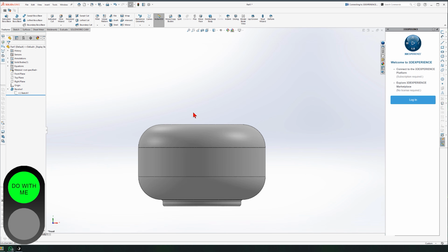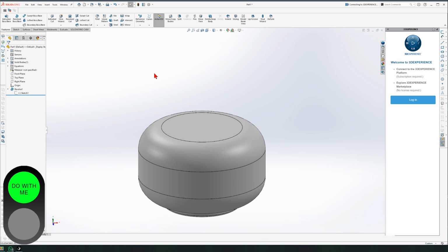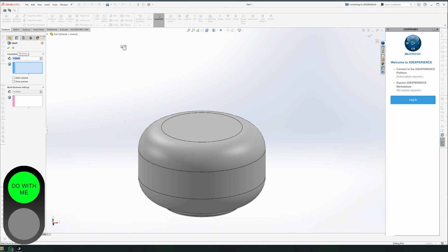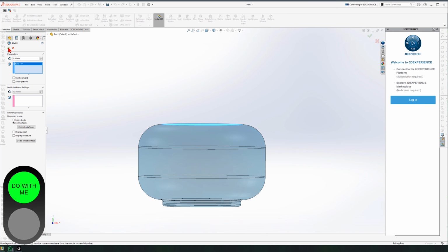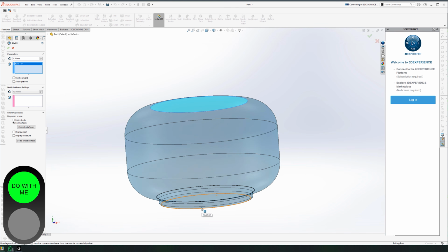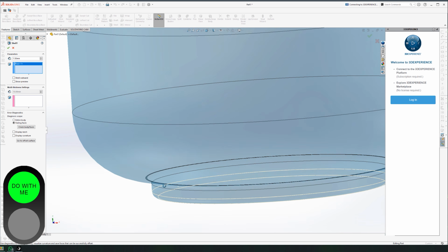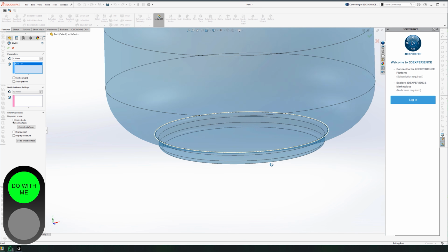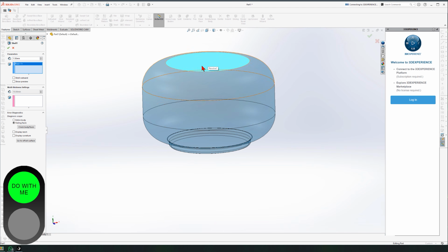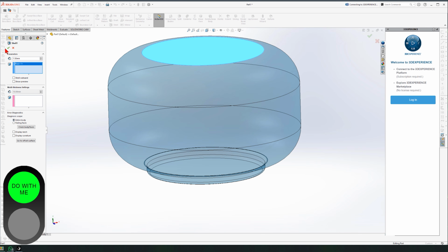Next, we're going to do the shell. The wall thickness is about 1.5 millimeters. Opening from here. So we go to shell, set it to 1.5, and we select this top surface, and we'll click OK. This gives us a problem here. In this case, because we have very narrow bends here, it cannot shell it with 1.5. Let's just say entire body.